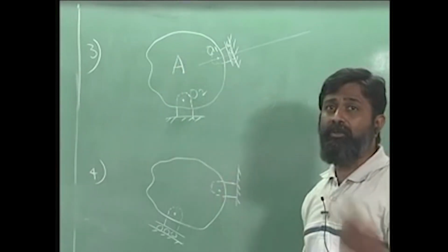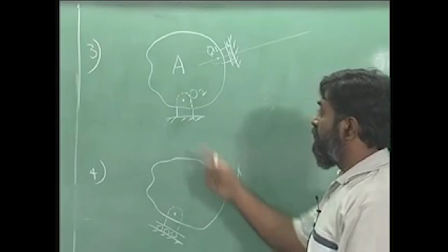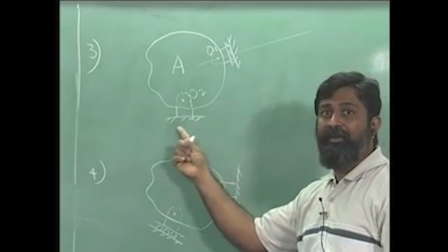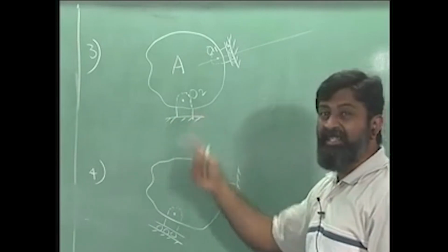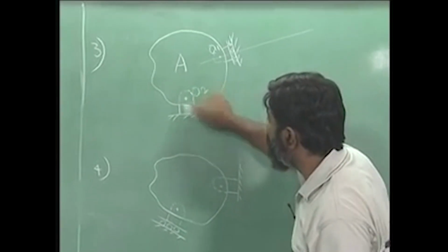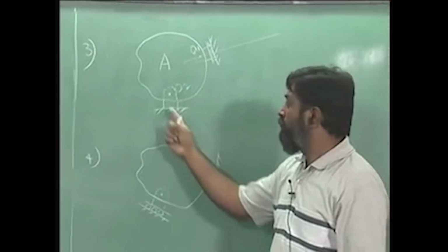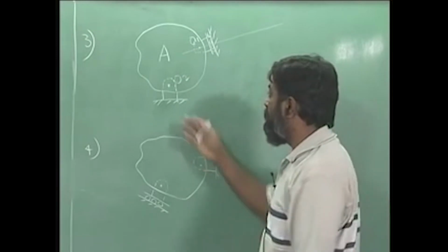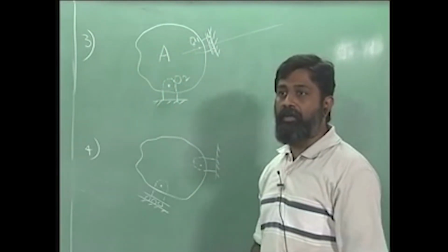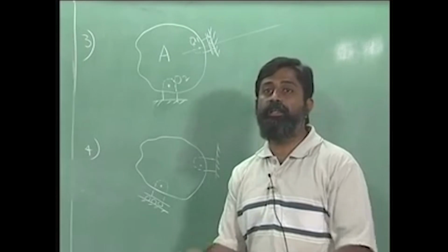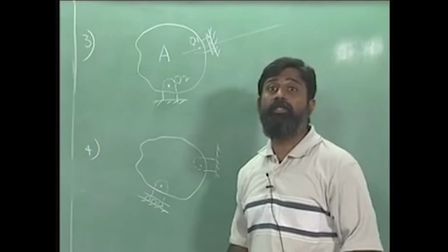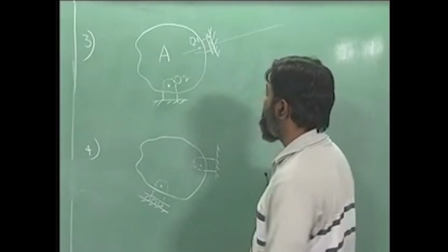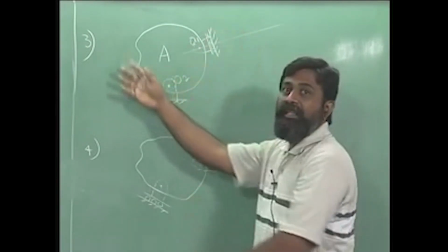Body A would have had 2 degrees of freedom. Since I am doing this also, if you look at this, this is a pin joint or a hinge, and this arrests motion of O2 in x as well as y direction. So in all, if I look at this particular rigid body and ask how many degrees of freedom it has, or in other words in whatever ways it can move, the answer is if I do this it cannot move at all,